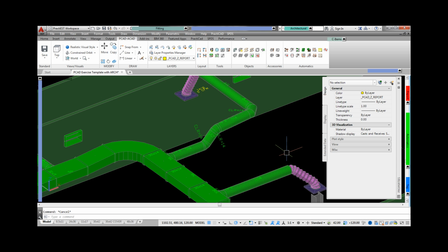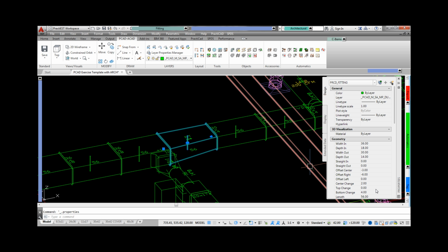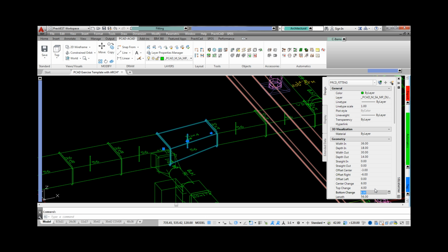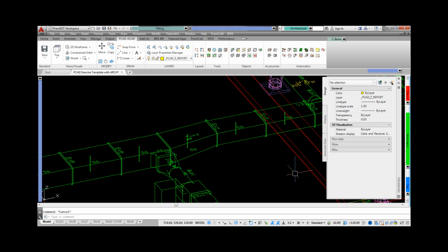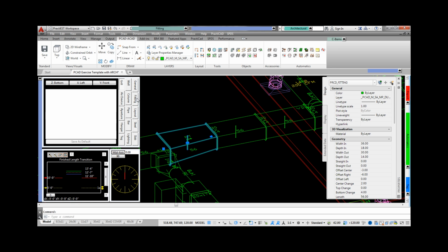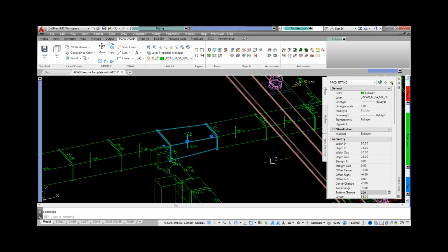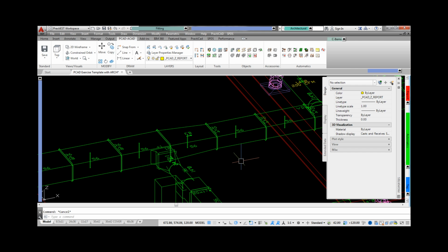Notice the little blue arrow on the transition indicating the direction we're going to try to make a change. First, we're going to edit the duct line forward. Then we're going to use the PCAD parameter box, reverse the airflow direction, and edit the duct line backwards. We can actually isolate fittings off the run to make changes, edit duct line forward, duct line backwards, from one point to another, or even globally edit the entire drawing. This includes updating the specifications. And there's even more options available.